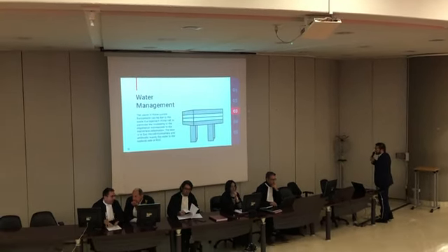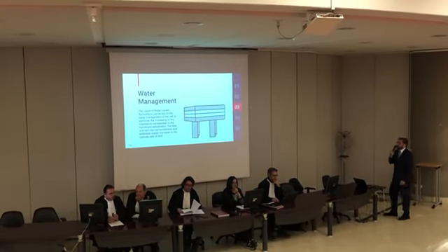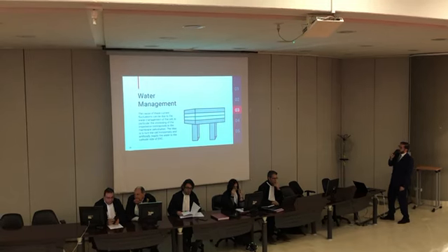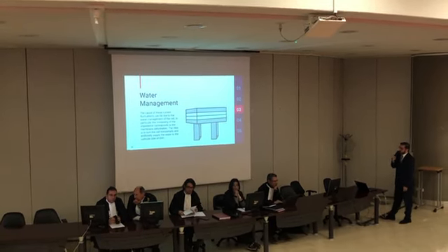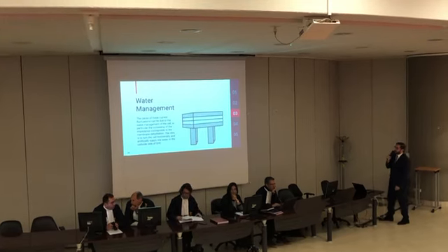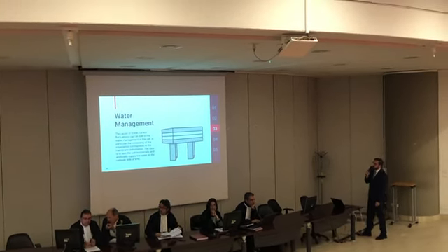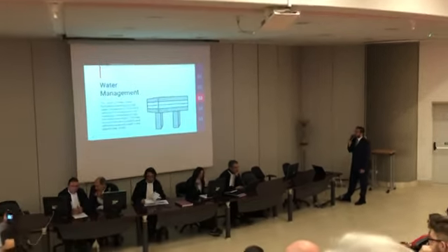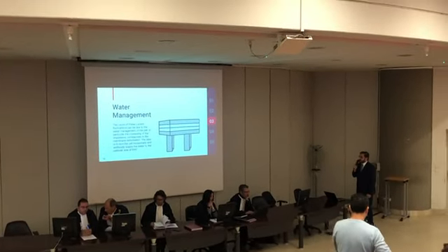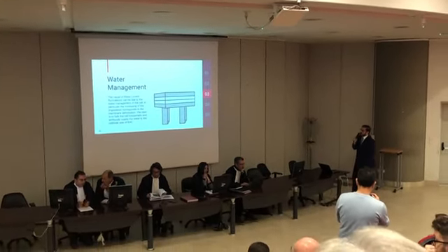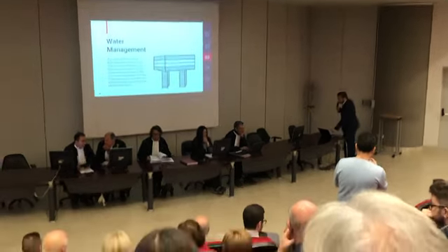The last attempt regards the water management. In particular, the cause of this current fluctuation can be due to the water management of the cell. The increasing of the impedance corresponds to the membrane dehydration. So the idea was to turn the cell in horizontal position using these two legs and to supply water artificially to the cathode side.